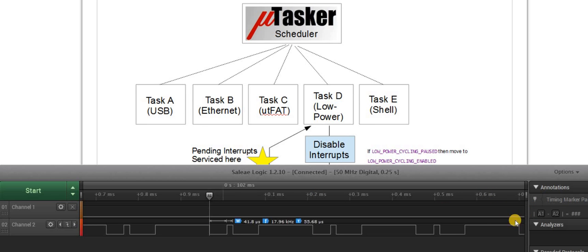What we see here is a cycle. The cycle is repeating at about 250 microseconds. So this is our basic operation. This point here is when we wake up out of the low power mode. This is the handling routine, and at some point in time we go back to the low power mode again. So what we see is that the amount of work required by the scheduling to wake up, to do its work, to go back to the sleep mode is taking up almost half of the cycle period.